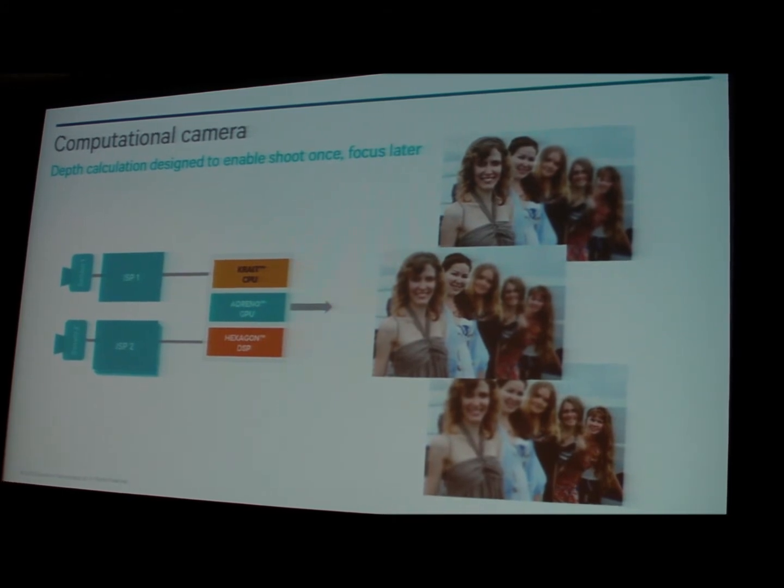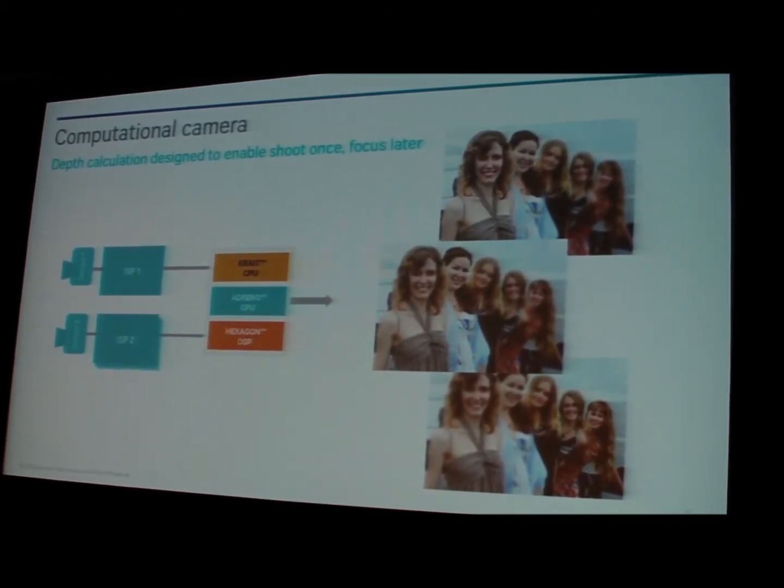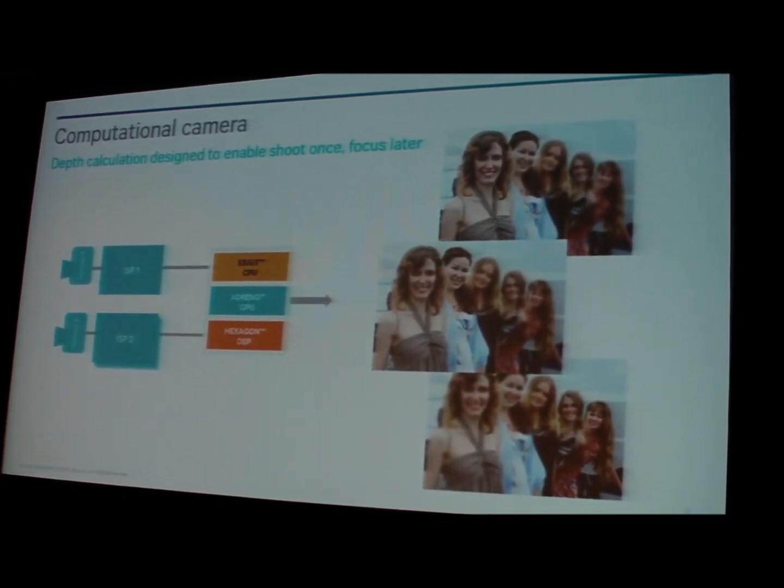And we have sufficiently high throughput image signal processing hardware that you can take several pictures in burst mode at different focus points, so you can adjust the actual focus value on the hardware. By doing so, you can allow, in a camera application that might run on your mobile device, essentially user selectable focusing of the images that you gathered.